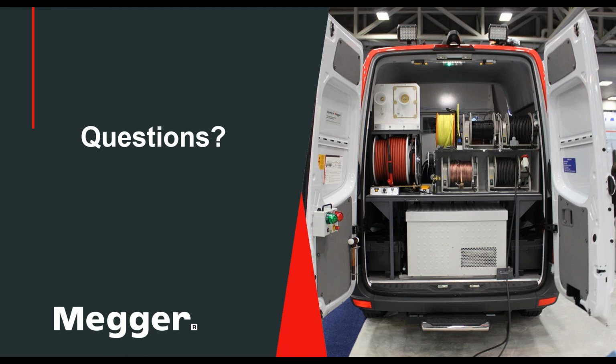So that has not much to do with the fault locating, unless you have a low voltage cable. Low voltage cables in Europe are typically not armored, so you have no shield and no armor, so basically you do fault locating phase to ground. And when you have a low voltage cable that has an armor, it can serve, so to speak, as a shield.